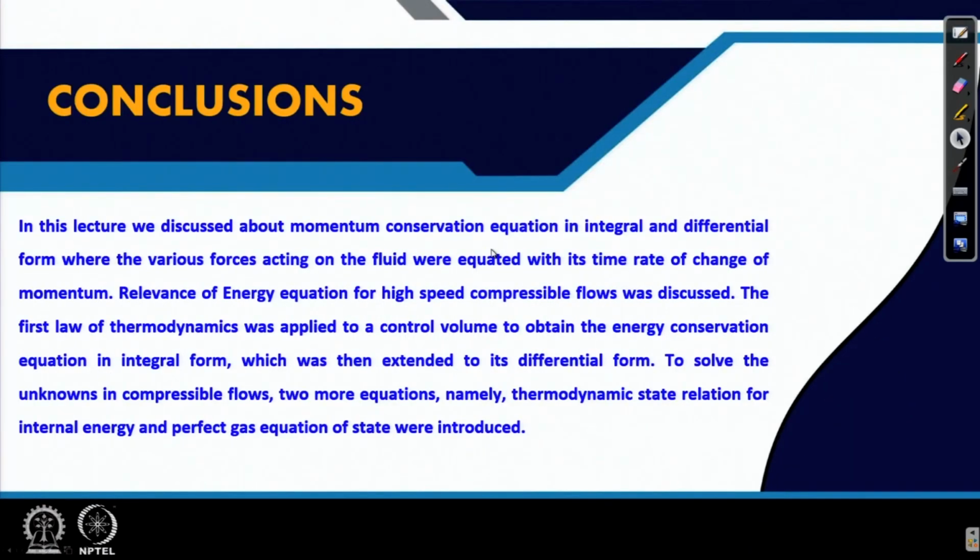So, we will conclude this lecture by saying that we discussed the momentum conservation equation in integral and differential form, where various forces acting on the fluid were equated with its time rate of change of momentum. And then the relevance of the energy equation for high speed compressible flows was first discussed. Then the first law of thermodynamics was applied to a control volume to obtain the energy conservation equation in integral form.